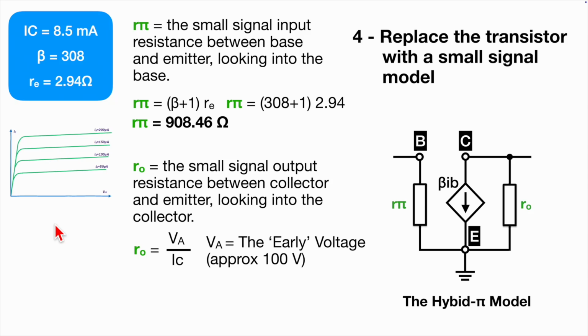I'm not going to get into all that now, but essentially what happens is as the collector to base junction gets increasingly reverse biased, as the collector to emitter voltage increases, so does beta, so does the gain a little bit, which means that the collector current increases, and so we actually get more collector current as the VCE increases.